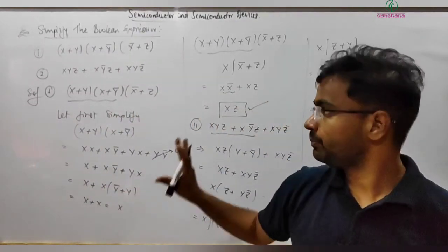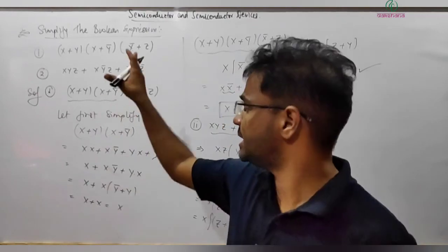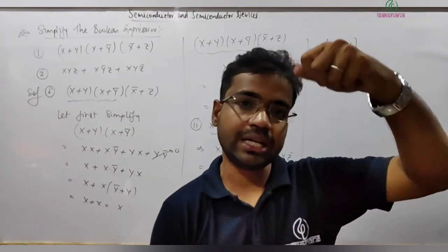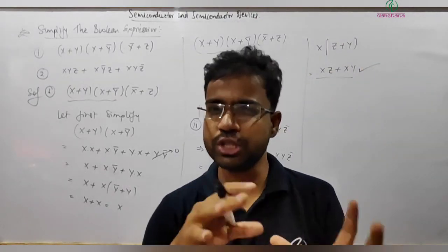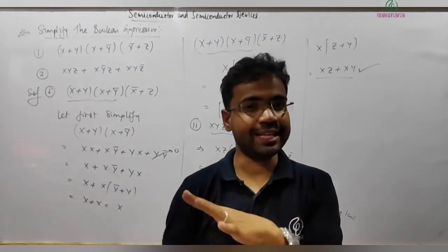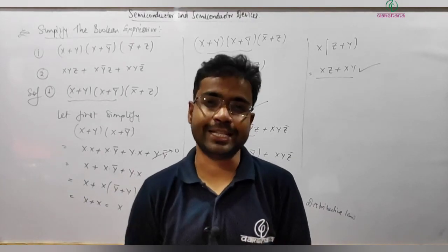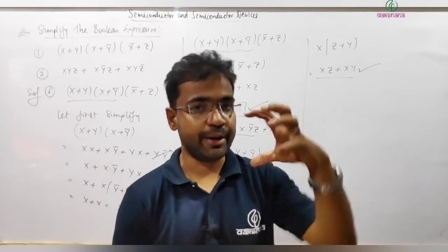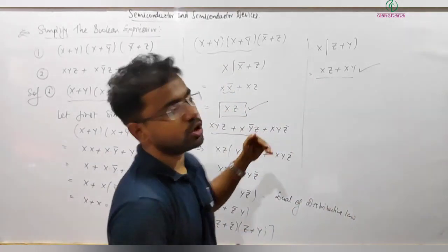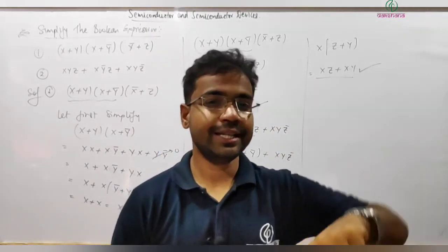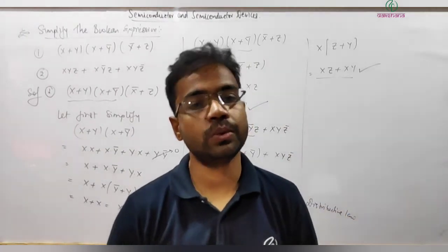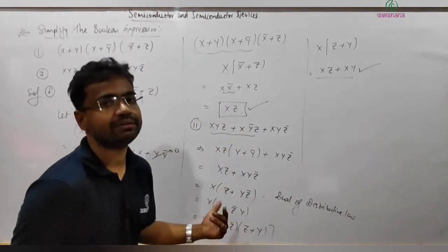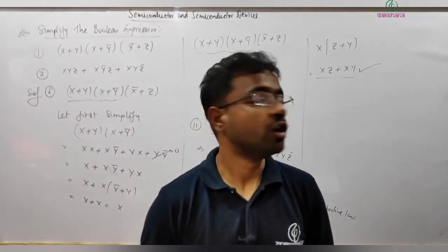So this is the application. In this, first, somewhat complex expressions are given, or some logic gates will be given in different combinations, and you will be asked what the final result is. So what you can do there is just write the Boolean expression according to the logic gate, apply the operation and get the final expression, and then from the final expression you will be able to comment on what exactly it is. That is the way it will help you in solving and simplifying problems.